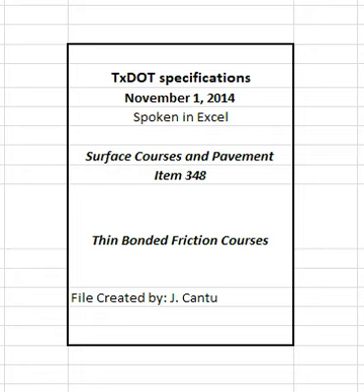Table 9. Testing frequency and mixture production tolerances. See table in specifications. 1 only applies to mixture produced for Lot 1 and higher. 2 Aggregate gradation is not allowed to be outside the limits shown in Table 7. 3 Ensure the binder content determination excludes fibers.